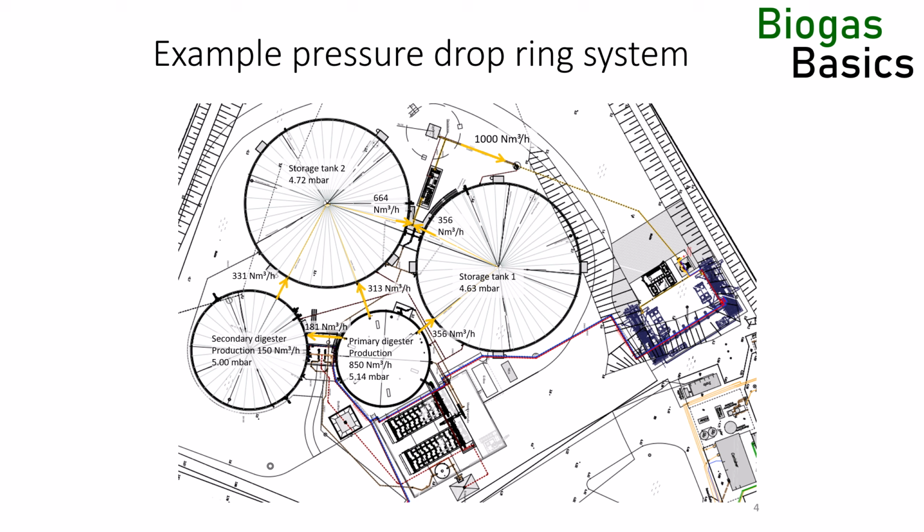Here is the example biogas plant from the first part of this mini-series again. It has two CHPs. The first 1200 kilowatt CHP operates as baseload and provides high-temperature heat to an amine scrubber of a neighboring biogas plant. A second 1560 kilowatt CHP provides peak load during times of high energy demand in the grid. In this application, the plant must store and discharge biogas from the gas domes.